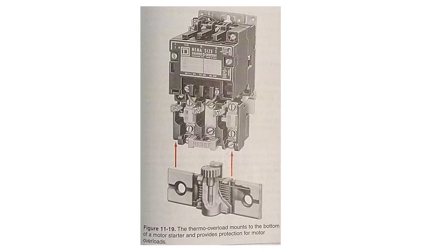Overload protection. Overload protection can be provided through one of several methods. The method used depends upon size, type, and application of the motor. The circuit feeding power to the motor is usually protected by a fuse or circuit breaker. A fuse or circuit breaker provides the best method of protection against damage from short circuit or locked rotor conditions. Locked rotor is a term that means the rotor is not turning because of a physical impediment while the power is applied to the motor. An actual overload protection is usually provided by a thermal overload.